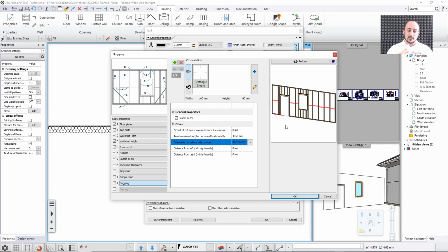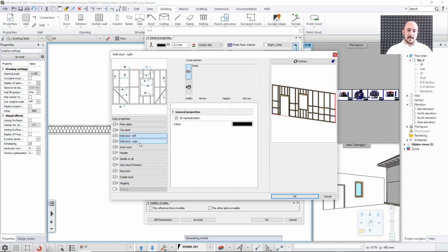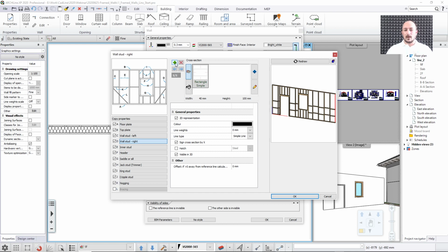This is how you can change it, and also you can change its elevation. And if you would like to, let me just change this elevation to, I don't know, 600 millimeters. So this is where it rests now. And if you would like to add an extra, you can do that by clicking on this one, and then you can just change its height to, I don't know, 1,300 millimeters. And you can just keep going and adding more and more of these. So wherever, in the case of these items, you can see an extra tiny green cross at the top, that means you can actually add multiple layouts, multiple sets to this same wall structure, which helps a lot, especially when you would like to create, I don't know, two columns next to each other in two separate layers.